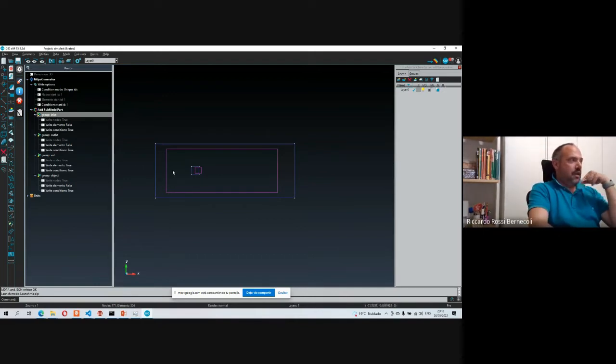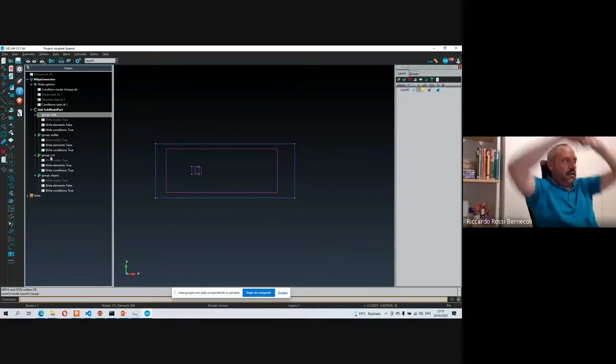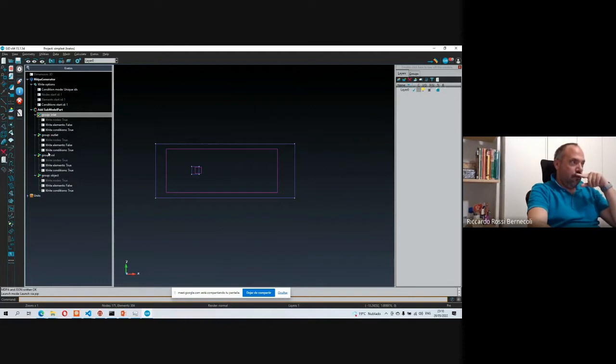Here, specifically, what we add is, for example, an inlet, an outlet, an object, and a volume. We have a mesh, which in this case is very coarse, but it doesn't matter. Essentially, we want to tell that, for example, every triangle in this, which is an element for us, is written in the group volume. A group inside Kratos is called a submodel part. We also want to have in this group volume the faces, although we may decide not to have them. There's no problem with that. And the nodes. For all the groups, we are telling what kind of information needs to belong to or be written in the group.